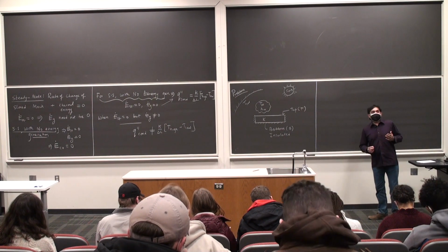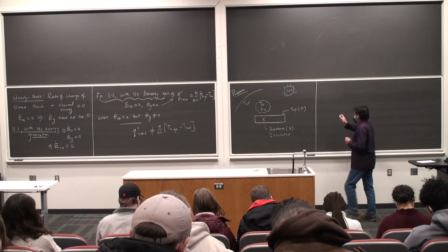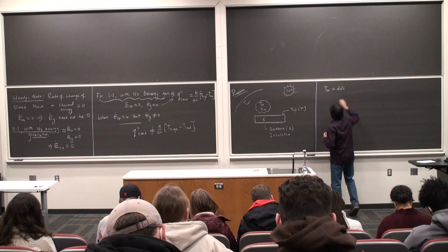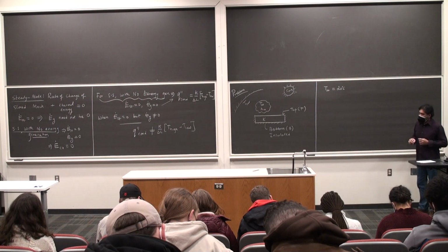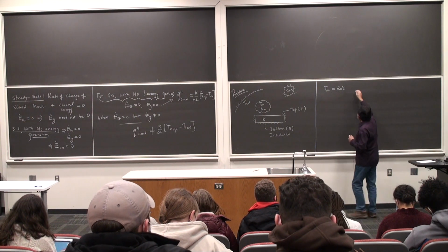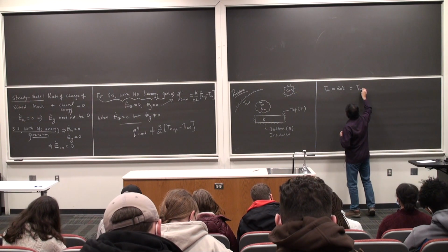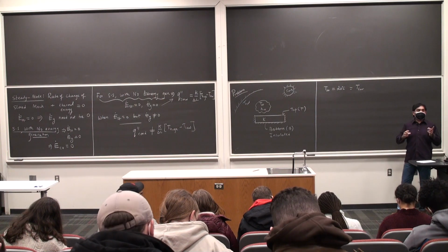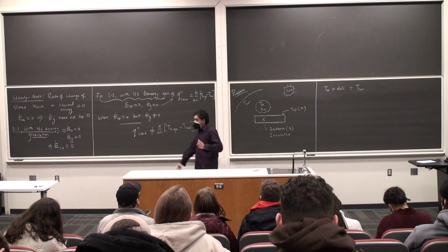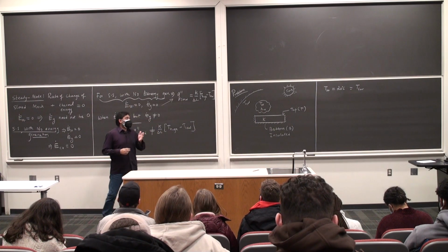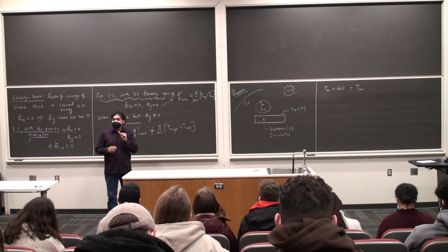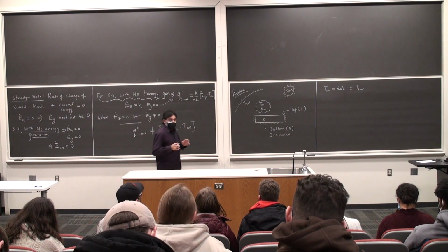The following information is given to us. So T infinity is 20 degrees Celsius. We are told in this particular problem that T surrounding is T infinity. In general, as you will see from the second problem of your homework, the surrounding temperature need not be the temperature of the fluid close to the surface. So this is something to keep in mind.